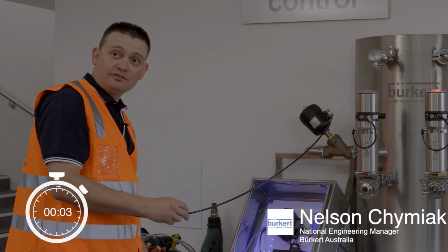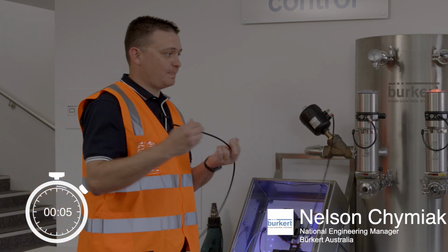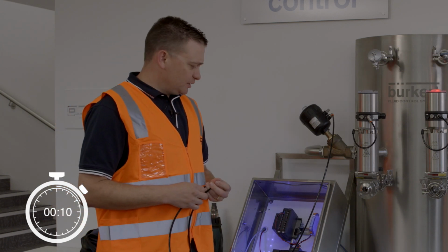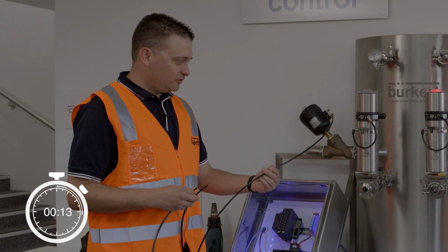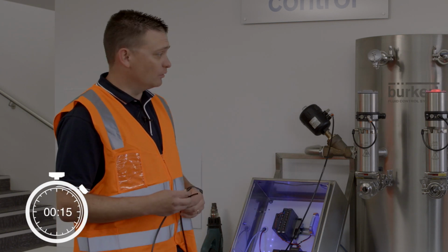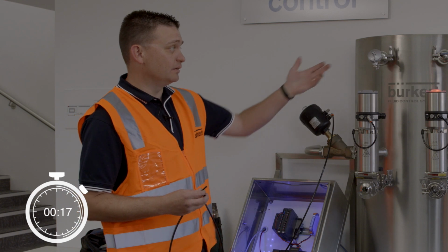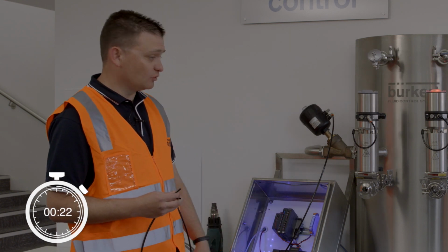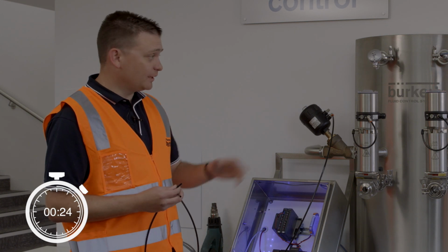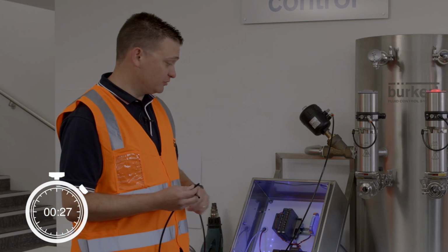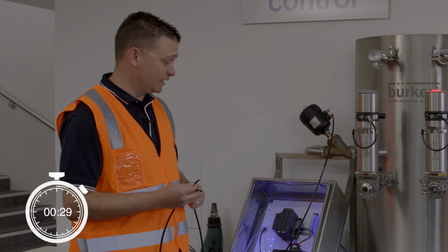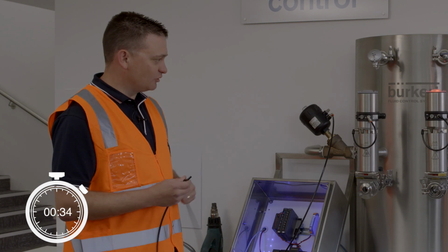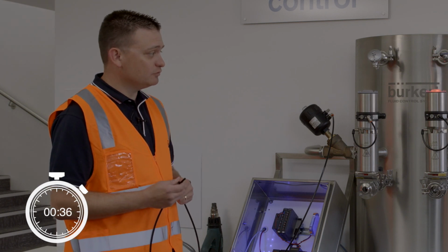Say hi. Hey, Chris. So just to give us a bit of an idea, how are you going to go about this? Yeah, so what I'll be doing first is obviously running the air tubes from the valves to the control panel. I'll then rough in my cabling, so that will mean cabling to the RTD and the control valve back to the control panel. Once all my cables are roughed in, I'll then terminate in the field and finish off by terminating in the panel and see how we go. And how long do you think that's going to take? Probably about half an hour, just given the type of job it is and what I've done before.